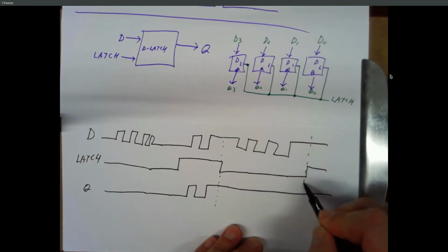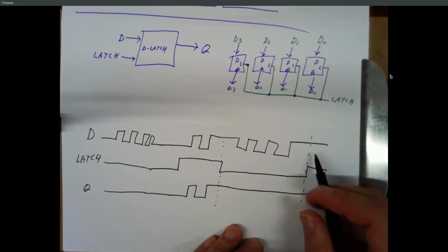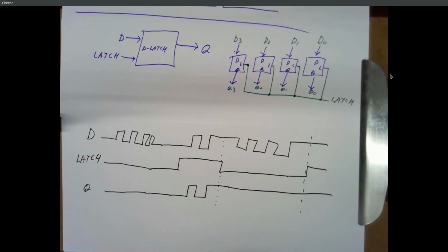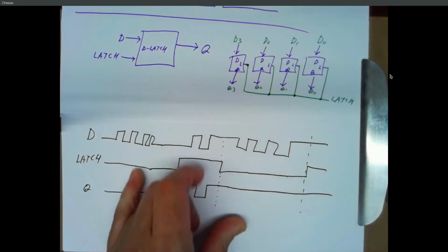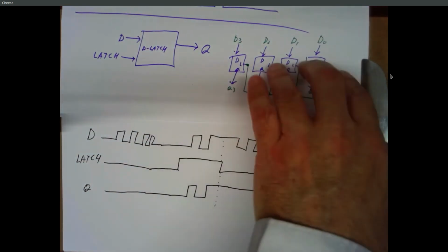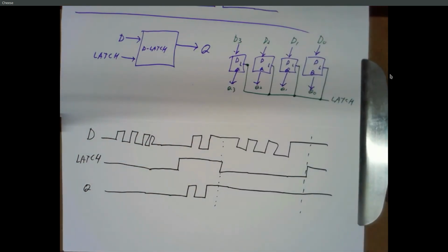And then when the latch goes to a 1, Q will pay attention to the value of D, and it'll show you whatever that value is. So that's nominally useful. We can store numbers or characters, or the Library of Congress if we have enough of these things, and put data in here. When we want to save it, just raise the latch to 1, drop it back to 0, and all those bits are stored in here.